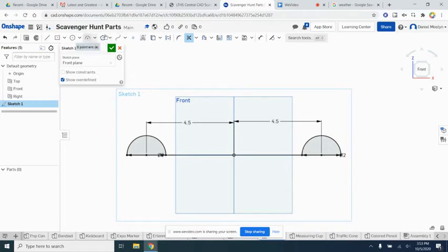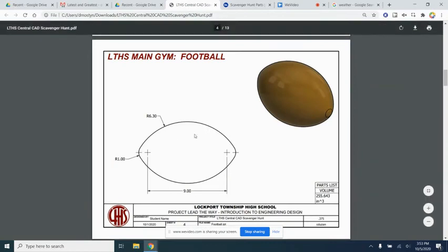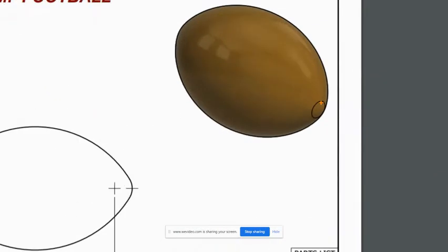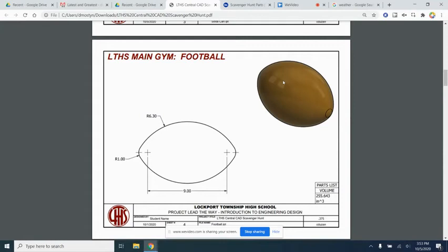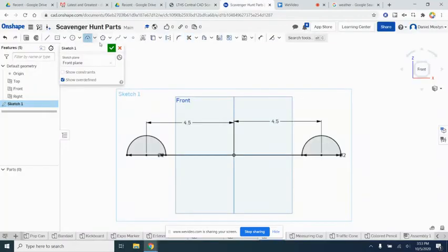We've got to be careful about this because if you look back at the drawing, at the 3D portion of the drawing, you can see that this little portion right here is the circle that we created. And then we have an arc that's going up. So the arc doesn't actually start at the corner. It starts a little bit farther off, somewhere over here where the circle is. So let's come back over this way. We're going to make the arc. Just pick somewhere on the circle, somewhere right about there, and somewhere right about there as well. And we'll just make our arc and not worry too much about it.